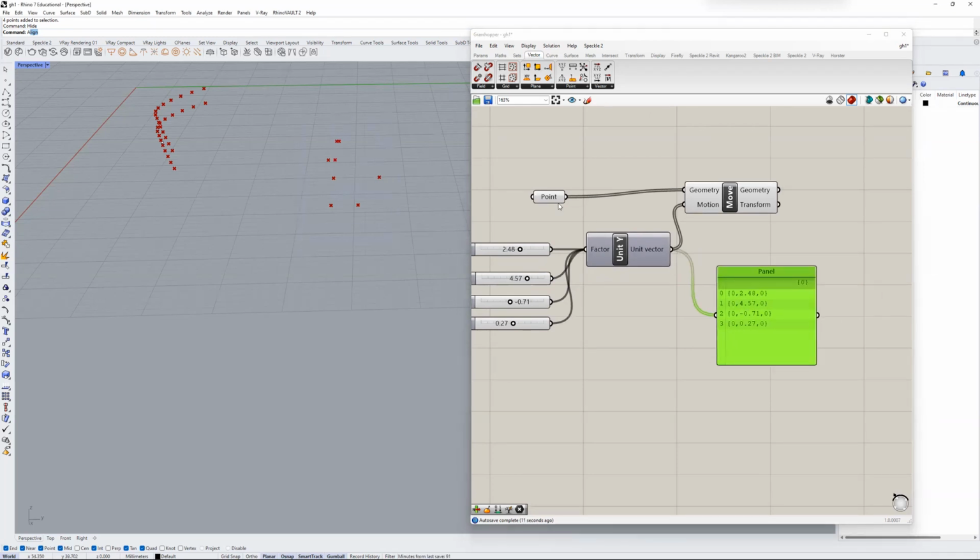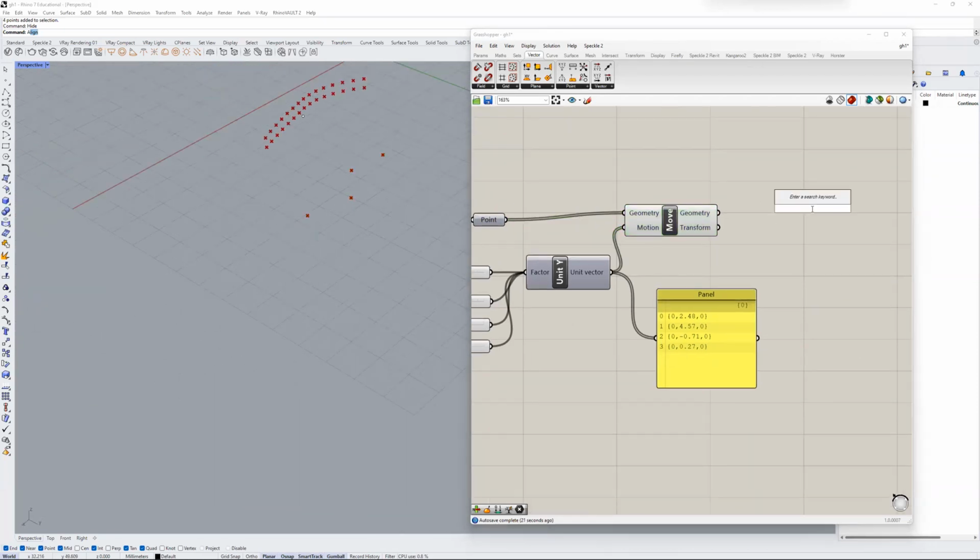There's a bunch of points here now, so I'm going to middle mouse button click on this and hide these points, my original points, so that I only see my moved points. Next, I'm going to create a curve, but there are lots of different ways to create a curve. If I just type in curve, you'll see there's NURBS Curve. There's more curves, I promise. There's Interpolate, which is an Interpolate curve. There's also, what was it? Polyline curve.